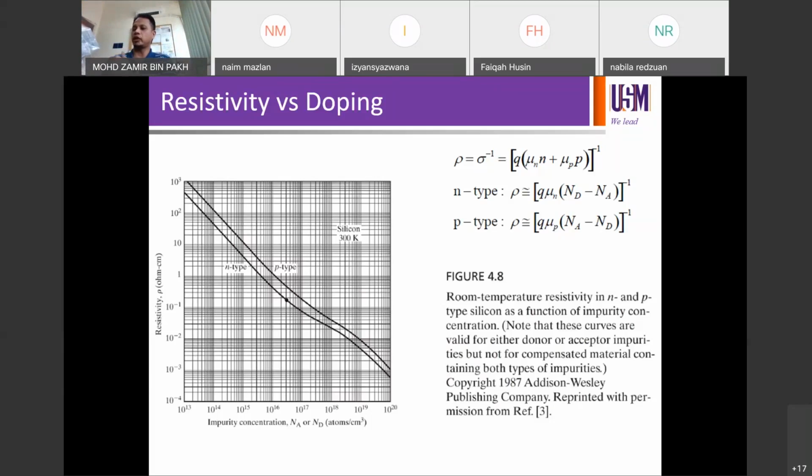Diameter 2-inch, 50.8 mm in the other unit, thickness is about 275 micron. The resistivity will be stated here as well. Resistivity in this case is 1 to 10 ohm cm, 1 to 10 ohm cm, as stated on your y-axis. So it means in this batch, they guarantee the resistivity variation between wafer 1 and wafer 25, altogether 25 wafers. So when you pick one randomly, the resistivity of the wafer that you have in the pack is somewhere between 1 to 10 ohm cm.